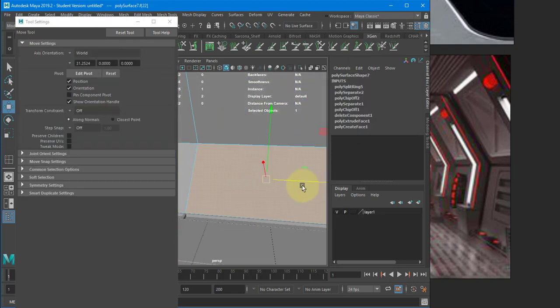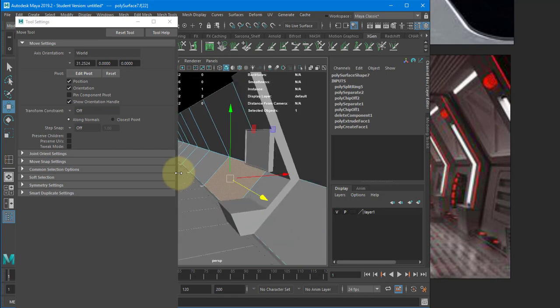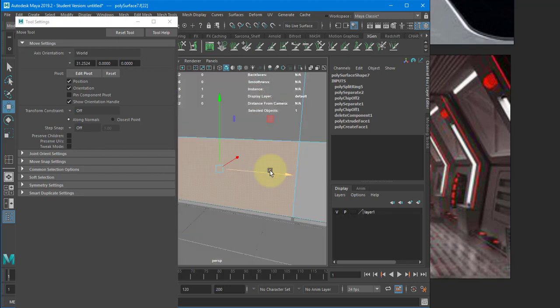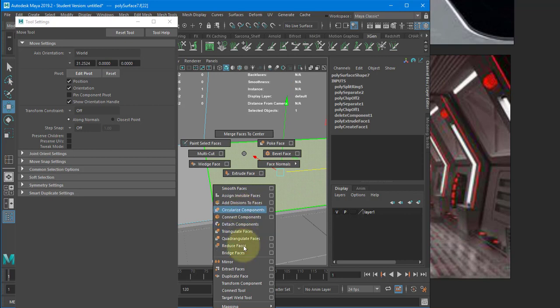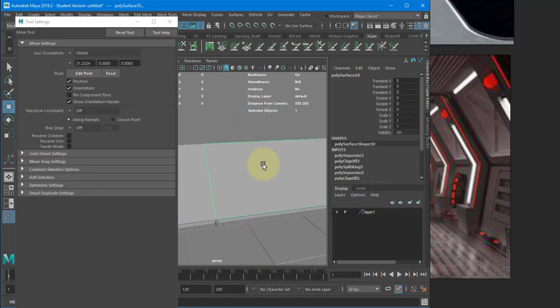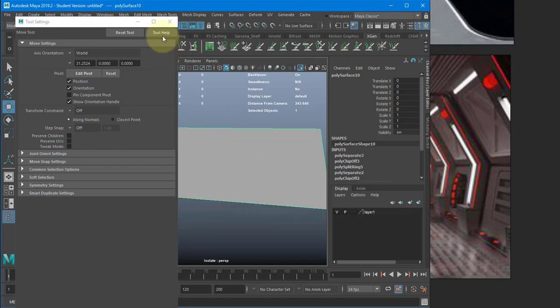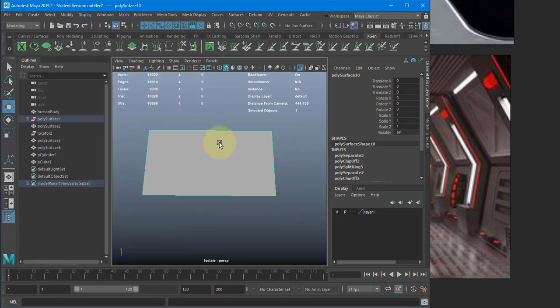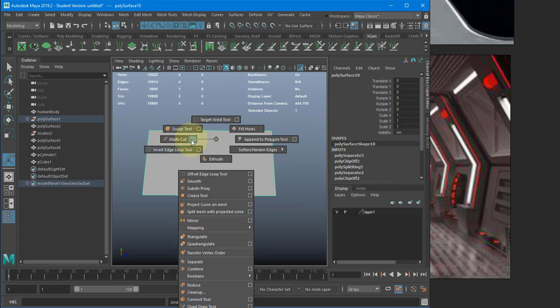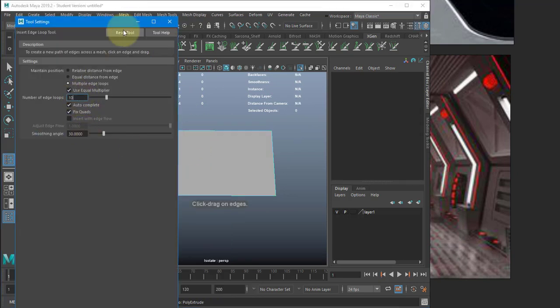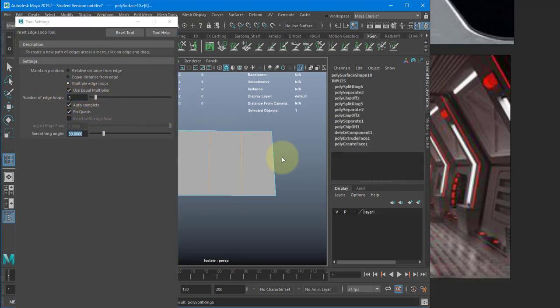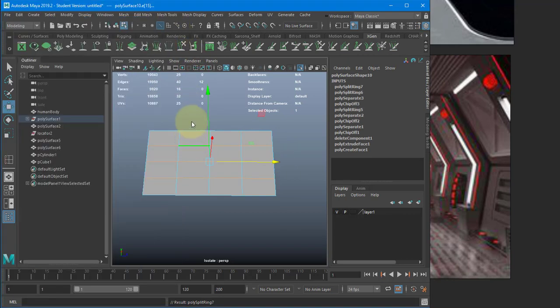And then each one of these panels here, I could customize so that I would have, let's say, different iterations of panels that I would use. So this panel I'm just going to use as my example panel, and I'm just going to extract this one. Okay, so he's all by himself. And then I'm going to customize what I want that specific panel to look like. So let's go and add some divisions to this. 10 is good. No, it's not good. 3 will be good. 3. That way and that way. And now I'm just going to go through and kind of tweak these different pieces.